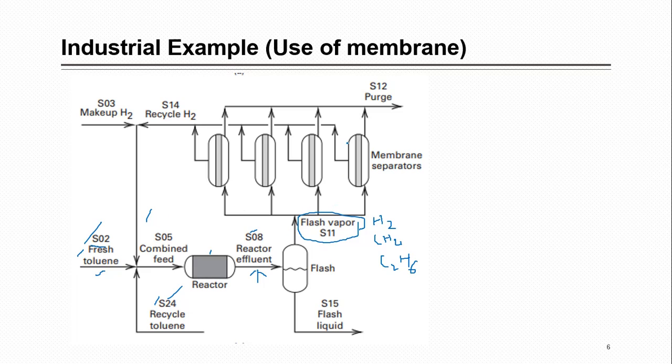But here a membrane was introduced, and that membrane has the tendency to separate methane from hydrogen. That membrane is formed of aromatic polyamide polymer. This is its material of construction, and its thickness is only 0.3 micrometer, 0.3 micron, very thin. It is a non-porous membrane that is used here, and that has selectivity for hydrogen. What does this mean?